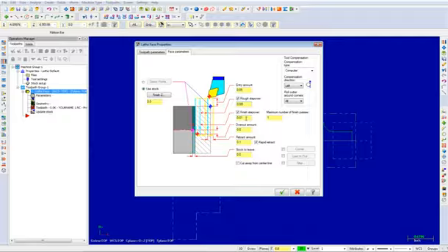Entry amount sets the height at which the tool rapids to or from the part. Rough Step Over sets the roughing passes value. Finish Step Over sets the finish pass value. Overcut amount determines how far past the center of the part the tool will cut. The retract amount determines the distance the tool moves away from the face of the part before it moves to the start of the next cut.